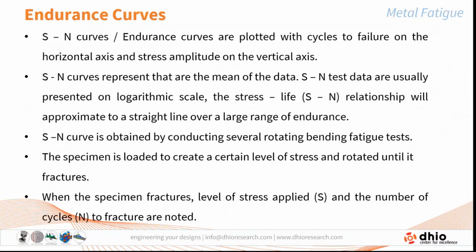Now, these S-N curves or endurance curves are plotted with the cycles to failure on the horizontal axis and the stress amplitude on the vertical axis. Since the number of cycles which you are going to consider sometimes goes beyond millions of cycles, in a conventional graph it would be a too cumbersome process to plot that. Instead, we plot in terms of a logarithmic scale, so that a large amount of data can be shown on the graph.